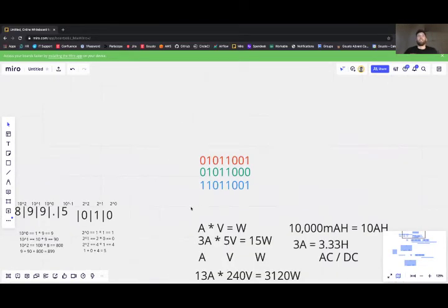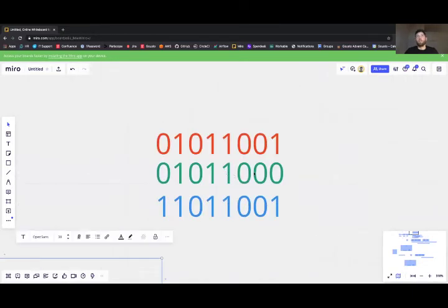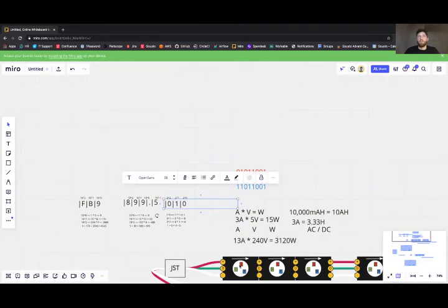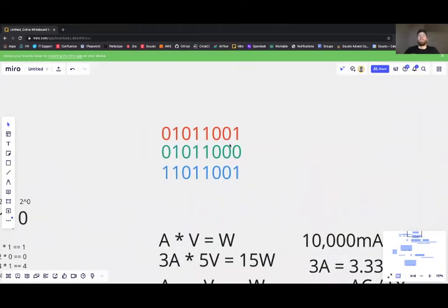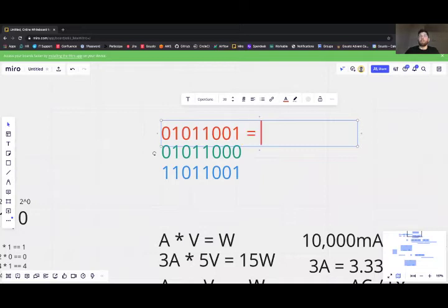Let's see just how these digital binary values are used to set the color here. Okay, so let's calculate their values. These correspond ultimately to the amount of current that will flow through each LED. So you're sending a digital instruction for the integrated circuit to increase or decrease the amount of current being sent to each LED. So here we've got 1 in the ones place.